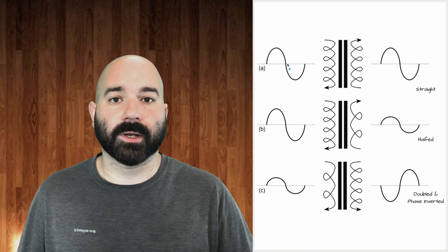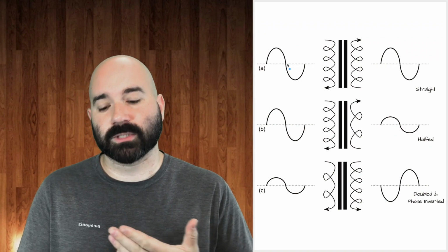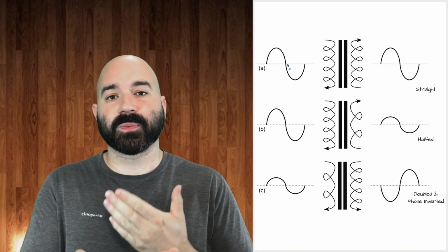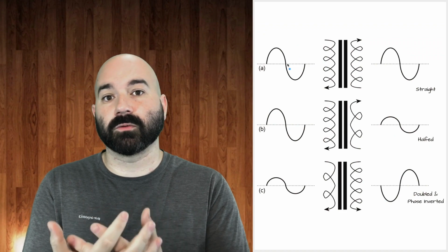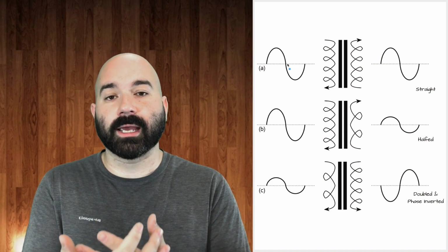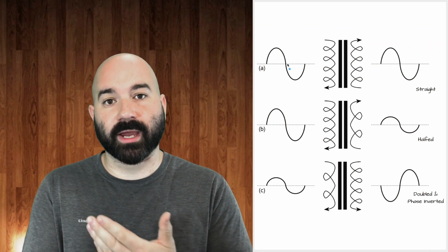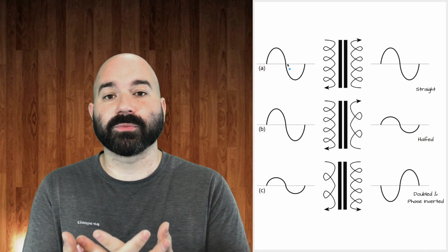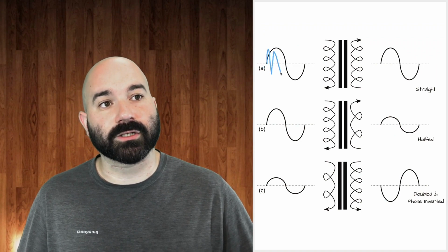So when we're talking about a microphone, like we learned in the last chapter, when the diaphragm, say in a dynamic microphone, is moved by sound pressure waves, that is going to move the coil of wire around the magnet and induce a voltage. How quickly that diaphragm moves back and forth due to the sound pressure wave determines how quickly the voltage will change up and down.